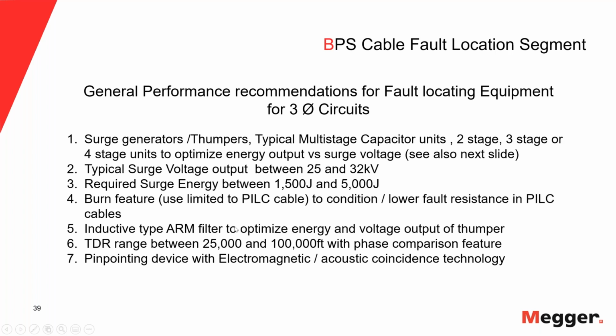All right, so going on, moving on, when we go to the fault locating itself, to the pre-location, it's very clear an inductive type arm filter is absolutely preferable over a resistive type filter, because any resistive type filter will suck out the energy that the thumper provides. So I use a big thumper with a lot of energy, and then I put a resistive filter in, so I'm defeating my purpose. So it should be an inductive type filter.